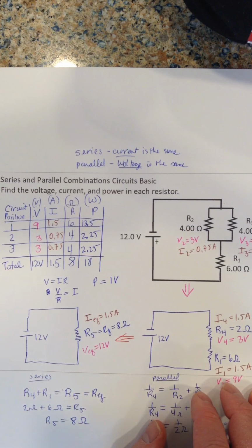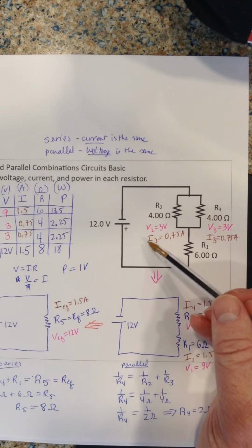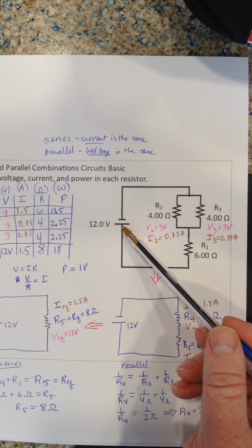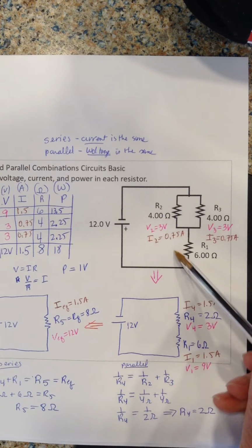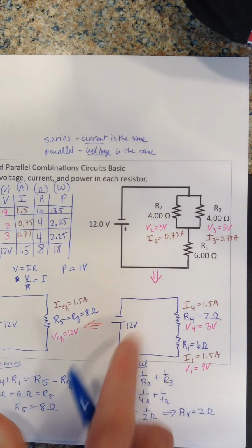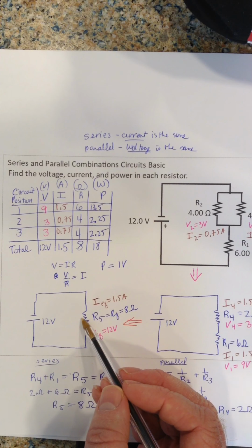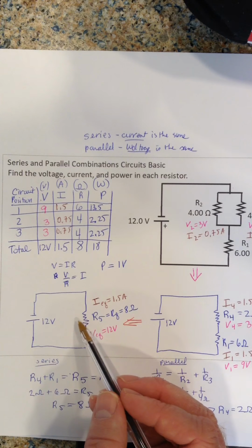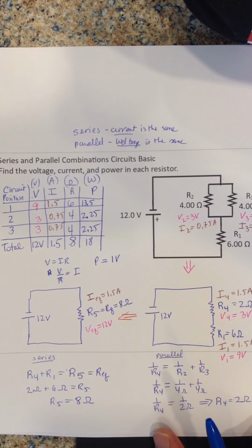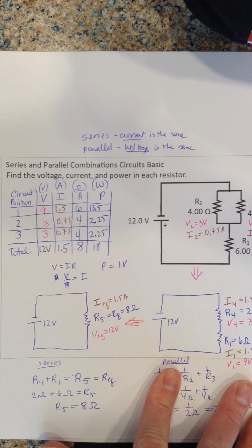So, in general, to solve a problem like this, you redraw the circuit starting with the stuff that's farthest from the voltage source, and you keep combining elements in series or parallel until you get down to one circuit that just has one resistor. Then to do the analysis you work backwards the other way to figure out all the different values. Alright, that's how you do it. It's tricky but not too bad.